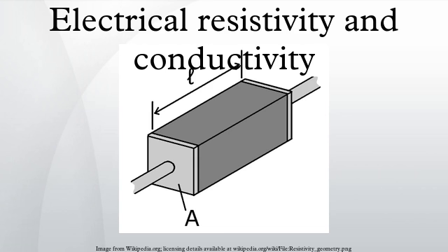Wood is widely regarded as an extremely good insulator, but its resistivity is sensitively dependent on moisture content, with damp wood being a factor of at least 10 worse insulated than oven-dry. In any case, a sufficiently high voltage such as that in lightning strikes or some high-tension power lines can lead to insulation breakdown and electrocution risk even with apparently dry wood.